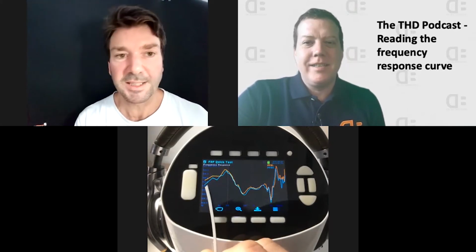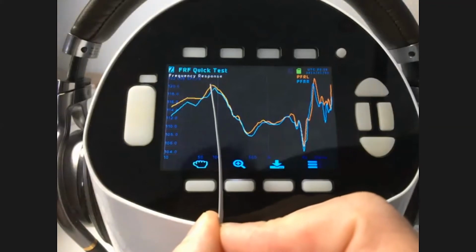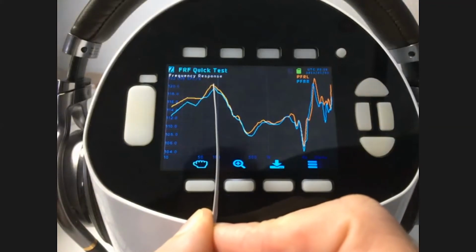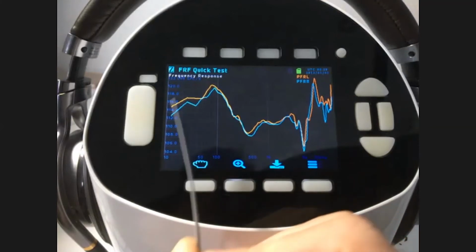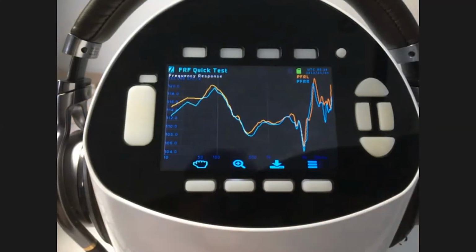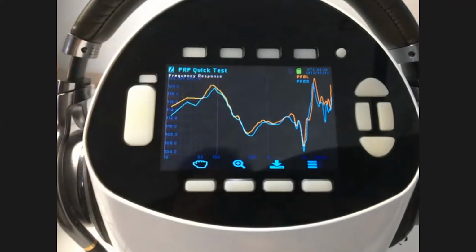First of all, you can see that it's a lot more busy and wobbly in the low frequency part. We've got the peak right there at 90 hertz, and then from 90 hertz, it's dropping off. So the lowest frequency is kind of 90 hertz. You'll still hear the sound below that, but that's just how it's set up. You might say, well, I'd like it to be totally flat along there. Well, it can be done. Again, it's one of those leakage issues, just as it is for an earphone.